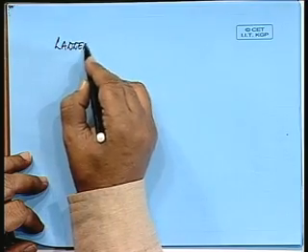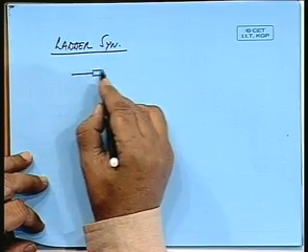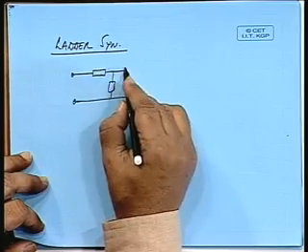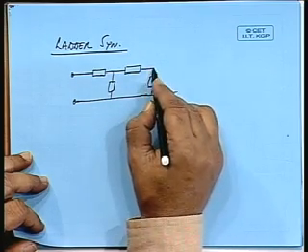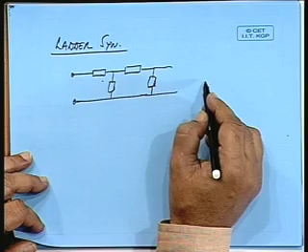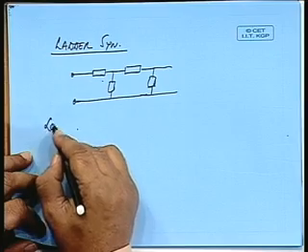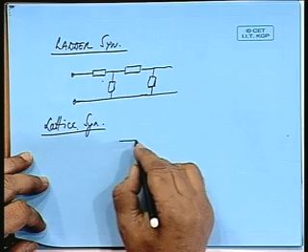There are two ways of realizing a two-port network. One is a ladder synthesis, that is, you try to go for realizing zeros of transmission in steps from one end, or there is another one, lattice synthesis, which we will be taking up later on. That is a very interesting synthesis.